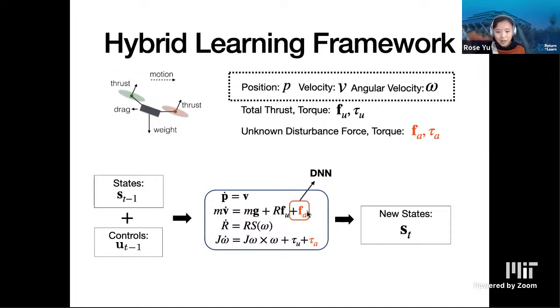So the simple idea actually did not work, right? The reason for that is deep neural networks are very flexible, but sometimes for learning dynamics, they can be too flexible. If they're too flexible, that will lead to unstable dynamics in control. So the final idea that we ended up with is something slightly different, where we need to regularize the behavior of a deep neural network with something called spectral normalization.